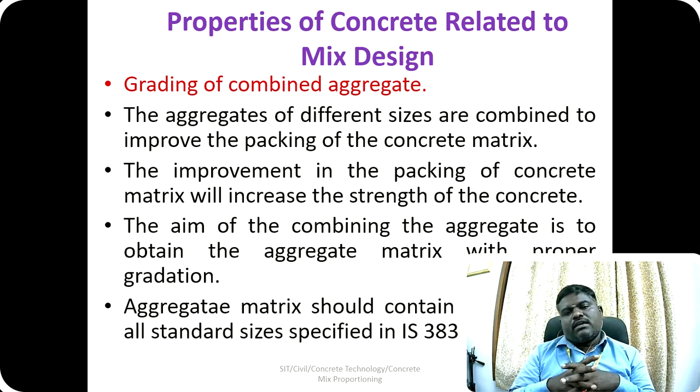If the packing of the concrete is enhanced, then automatically the compressive strength of the concrete will be increased, because the packing density plays a vital role in improving the concrete strength. The improvement in the packing of the concrete matrix will increase the strength of the concrete. Similarly, the aim of combining the aggregate is to obtain an aggregate matrix with proper gradation.